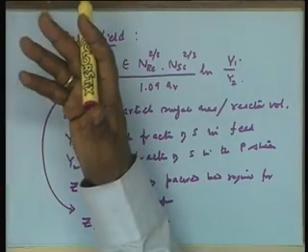That is fine, but suppose this Z1 is much greater than Z2, and then we are supposed to design a reactor based on diffusion limitations. Right, only Z1, you do not bother about Z2. So then will the length of the reactor be equal to Z1? Z1, right. You do not have to then bother about the biochemical reaction, because in that height the reaction would have already been possible to take place.